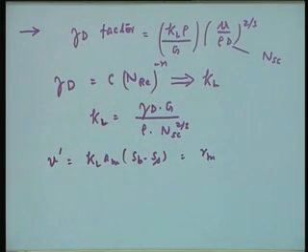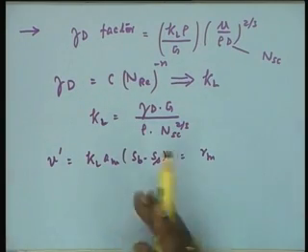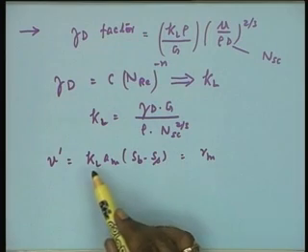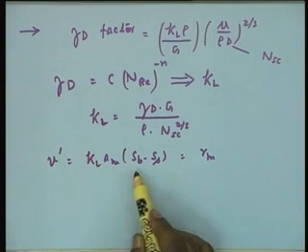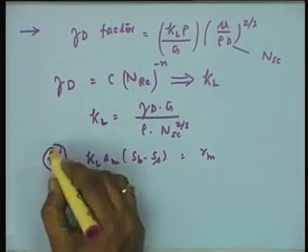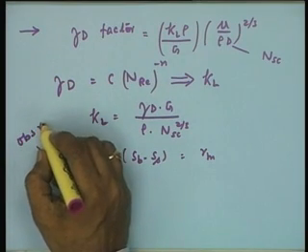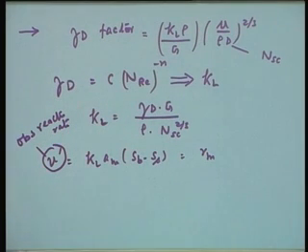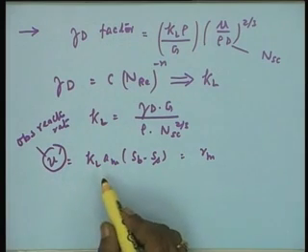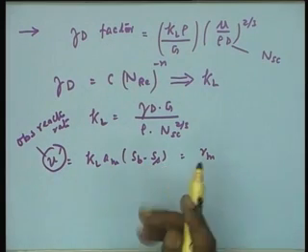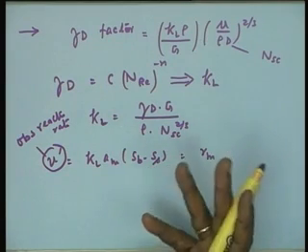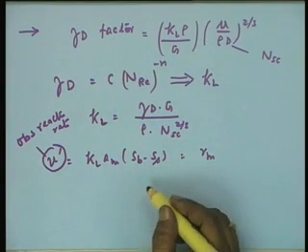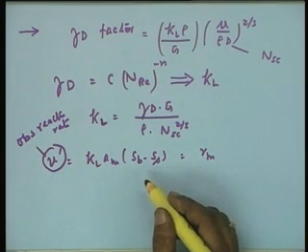The rate of mass transfer under steady state and the biochemical reaction rate are equal, and therefore one can get the magnitude of K L A m. Now this V can be considered as the observed reaction rate, which has been monitored experimentally, and therefore one can determine the magnitude of S p minus S s, and that determines whether the diffusional control is there or not, and accordingly one can design the reactor.